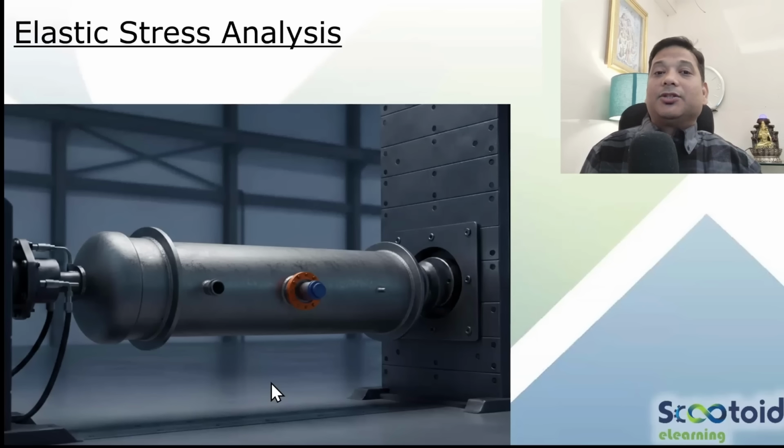Okay. So if I want to qualify elastic stress analysis, the first thing after pre-processing, when we say pre-processing, it is making the model, creating the meshing and doing the analysis. In the pre-processing and processing stage, your work is simple. You don't have to be very much an expert of the FEA tool.